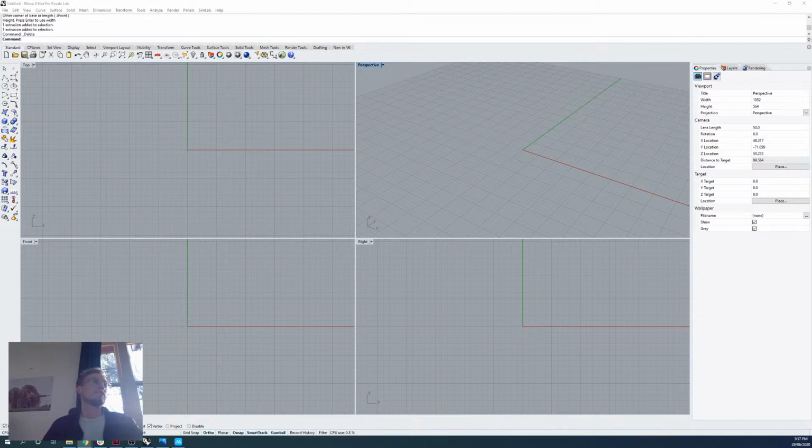You want to make sure you don't have gigantic texture files. If you have a texture applied to a geometry and it's a huge image size, that can create an issue. And then the last thing you want to do in terms of optimization is check if you've got any block instances. People use blocks, especially if they're going between Revit and Rhino. Currently, Fologram doesn't support block instances. It's certainly on our roadmap to do so in the future, but currently we don't support them. So just be aware, if you've got any block instances, explode them.